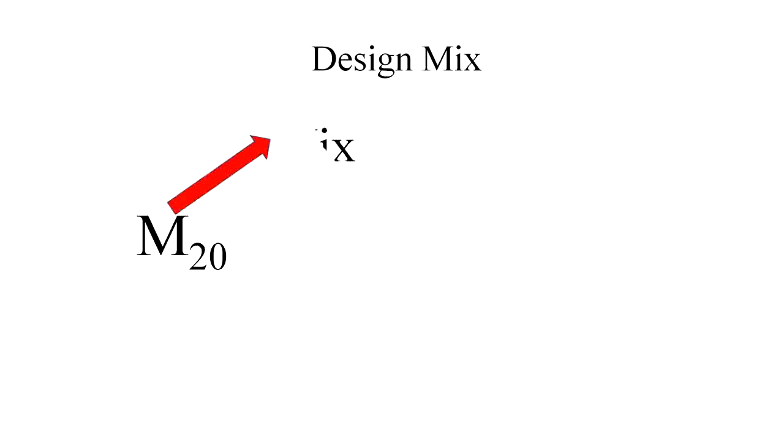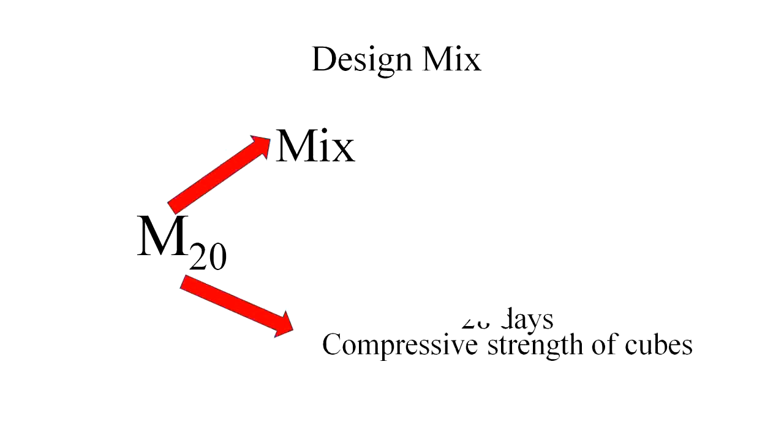The next question is, what is this design mix? Design mix is represented as M20, where M stands for the mix, and 20 is the 28 days compressive strength of cubes. The 28 days compressive strength of cubes will be explained in detail with the following animated video.